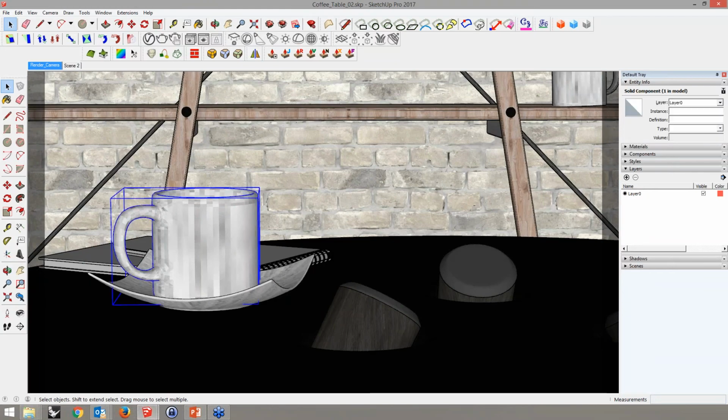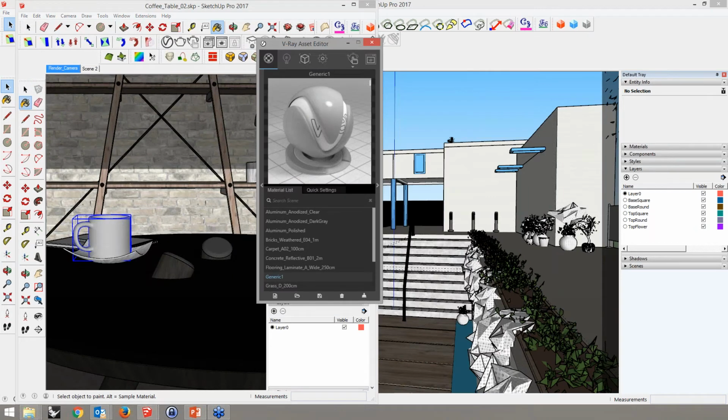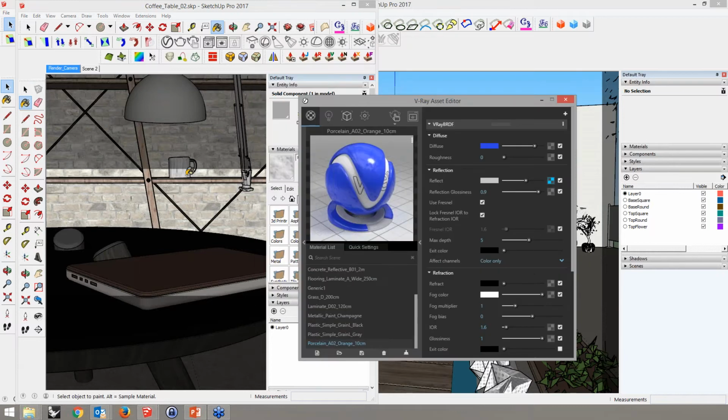So if I go to my, where's my material properties? Sorry, just bear with me for a few more seconds. No problem. So apply to material. There we go. So for some materials like this one, I'm not actually using a texture for the diffuse, but in order for UV mapping to show properly, the mapping of the textures to the surface, we need to show something in SketchUp.